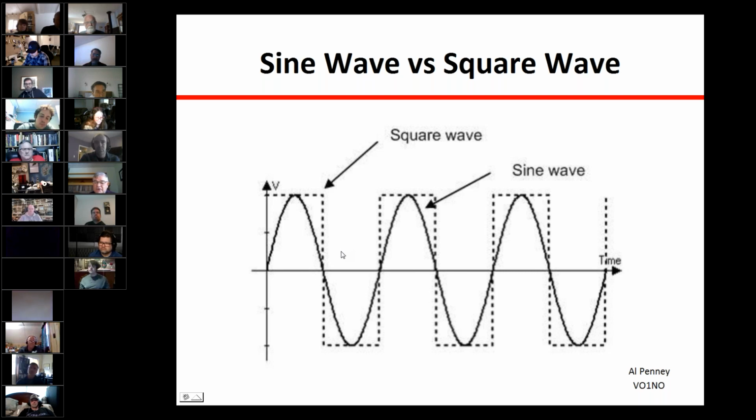Yeah, a pure or true sine wave. Some of them are not a very nice looking sine wave at all. Some of them are better when you're talking about those inverters. Okay, Jerry. A friend of mine picked up an inverter a while ago, so we took it to Fred VE1FA, and we measured the voltage and looked at it on the oscilloscope. You could see how the waveform was a little bit different from a sine wave, but it was actually pretty good, and there wasn't much interference.